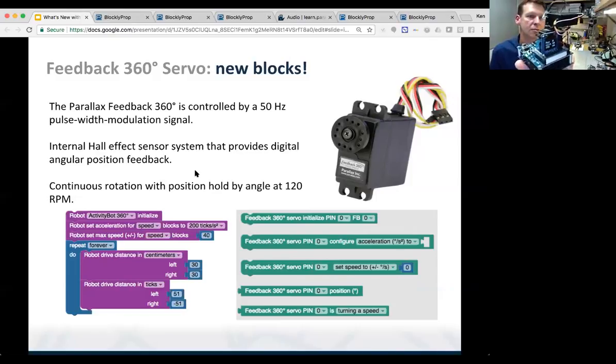Okay, I'll move it back a little bit. So as you can see, it's just rotating through, I think, 10-degree increments, and then checking 0 to 90 degrees, the distance with the laser, and then writing it to the display. So this could be used, I'm sure Carol has a lot of ideas, but maybe finding the most open area in a space so you can navigate freely with the robot.